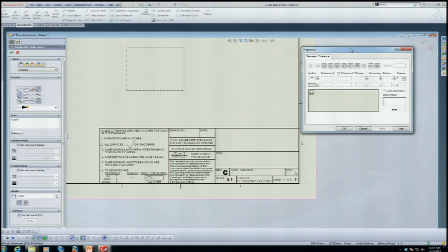And in many industries, it's not necessary to go through and try to dimension that model in the 3D space. That isn't something that you may need to do, especially if you just want to focus on critical to function dimensions. But you should still define the whole part. You should still give a tolerance to the whole part, in such a way that's clear.